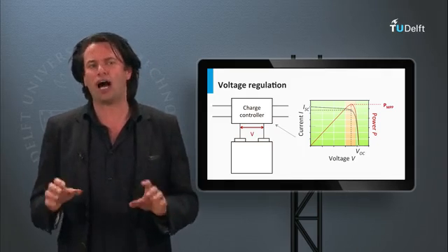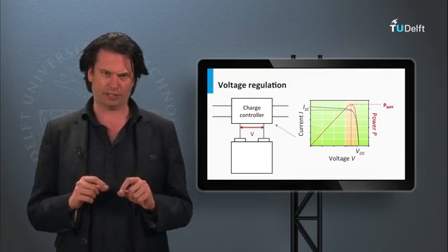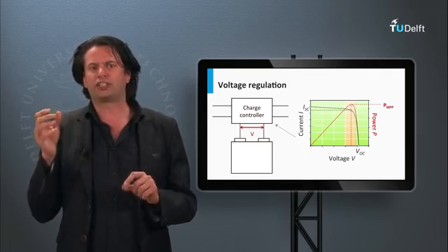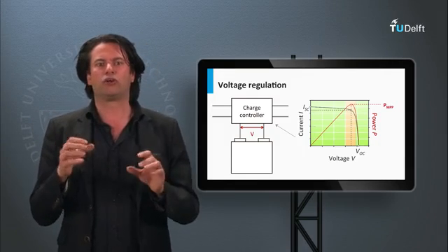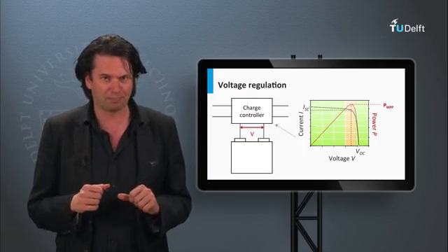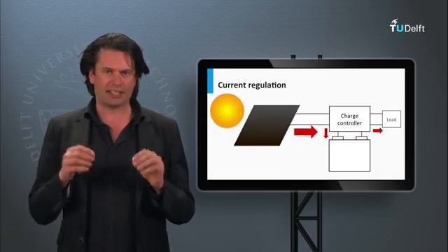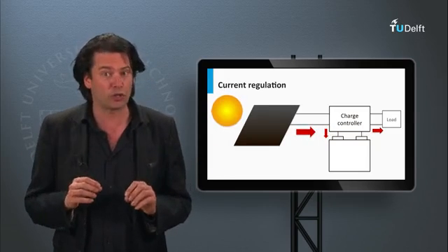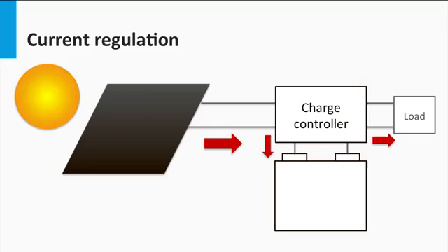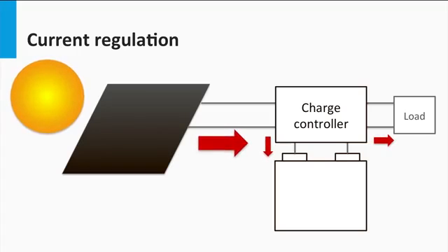We have seen before how the battery has certain C rates defined. Higher the charge-discharge rates, the lower the coulombic efficiency of the battery will be. The optimal charge rates indicated by the manufacturer could be adhered to by manipulating the current flowing into the battery. With proper current regulation, the charge controller is also able to control the C rates. At the very least, the charge controller can impose the limits on the maximum allowable currents flowing into and from the battery.